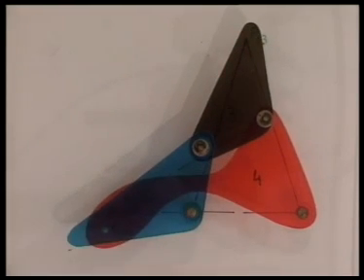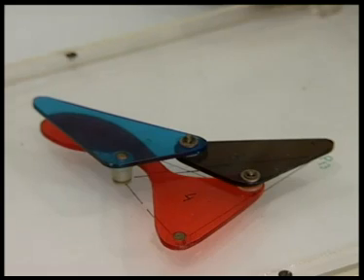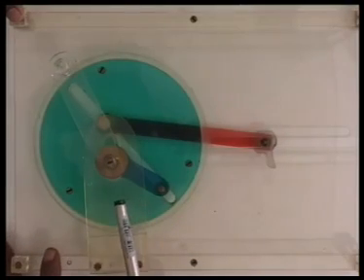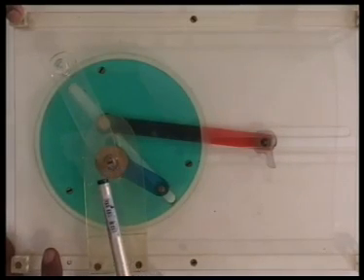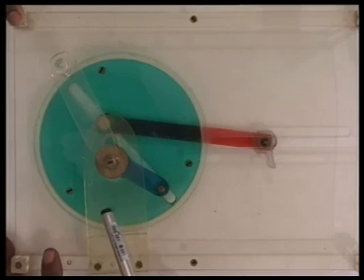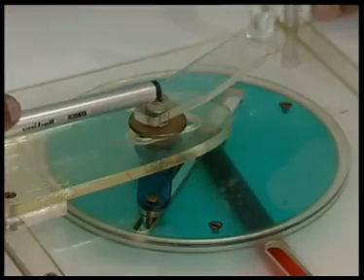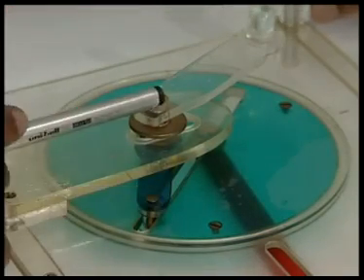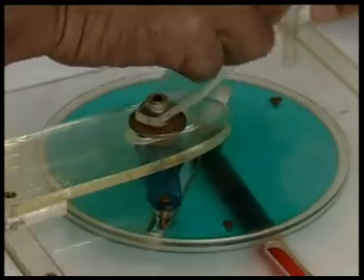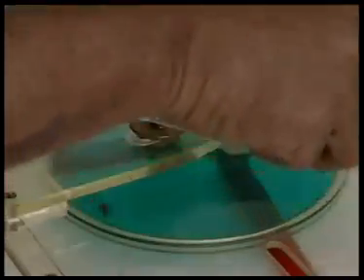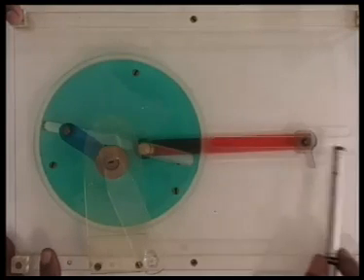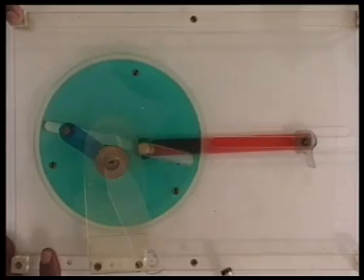At this stage, let me carry out another example of a 6-link mechanism. Let us consider the model of this 6-link Whitworth quick return mechanism, which we have seen earlier. Here the input link is this link, this is O2A. This is the input link which rotates at constant speed, and consequently the output link, that is the tool holder, reciprocates along a straight line.